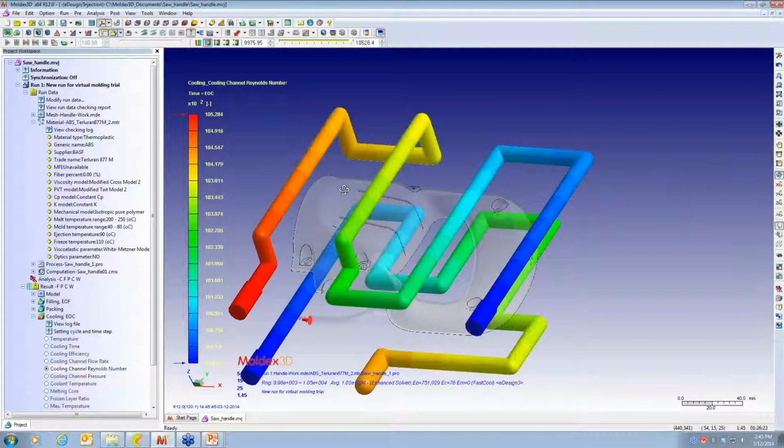The Reynolds numbers are a measure of the turbulence the water has while it flows through the circuit. So that's good to know. We discussed earlier that turbulent water is a good thing. And we can actually even look at the water temperature itself. As the water comes in this simulation, it's at 60 degrees. And at the exit, it's being shown about 64 degrees, which isn't bad at all. In fact, it could be taking more heat out.